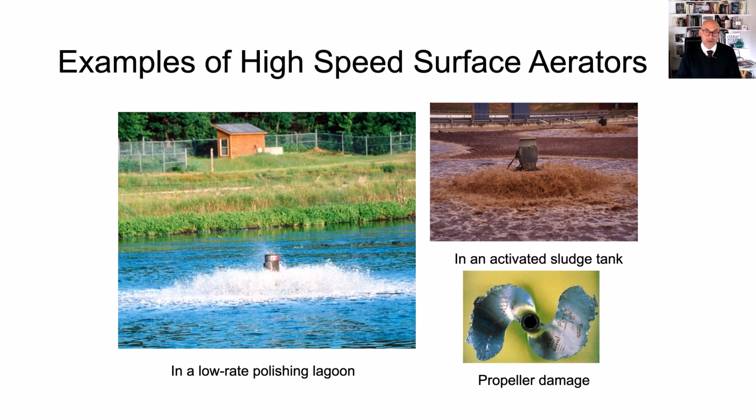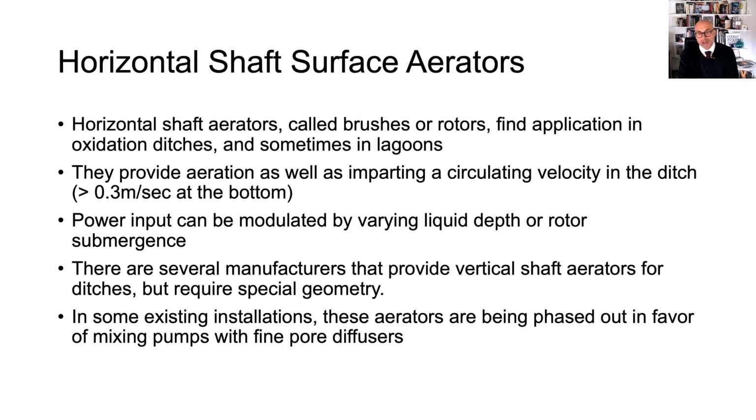And due to the high-speed nature, if you have any pebble there, it hits the propeller. That's the first thing to diagnose: you're going to have very poor performance if you have a propeller all chewed up by hitting solids in the lagoon.